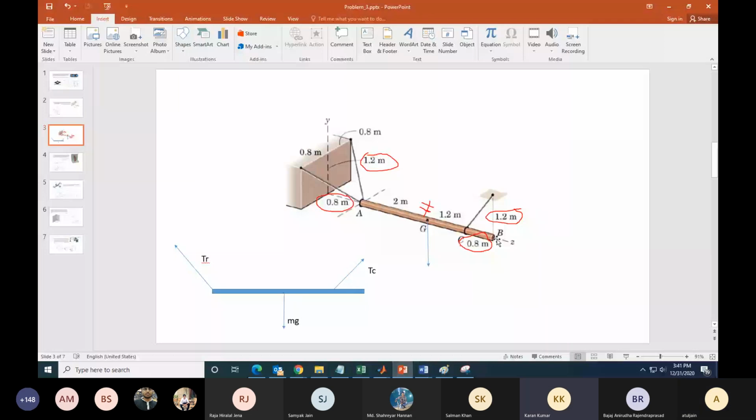Sir, I have solved it by taking moment at A. But you found now that it is not in equilibrium, correct? No, sir. By intuition, the moment has three components about C, sorry, two components, and about G, it has only one component in one direction. Yes, correct. That is also a good way of solving it. Let us take moment about point A. If you take moment about point A, mg will only have one component. TC will have two components. So individually, both the components cannot equate to 0. So the body will not be in a state of equilibrium.